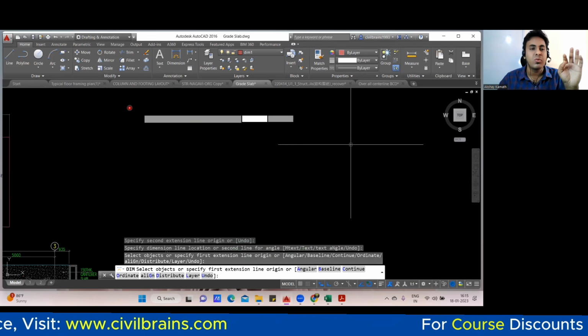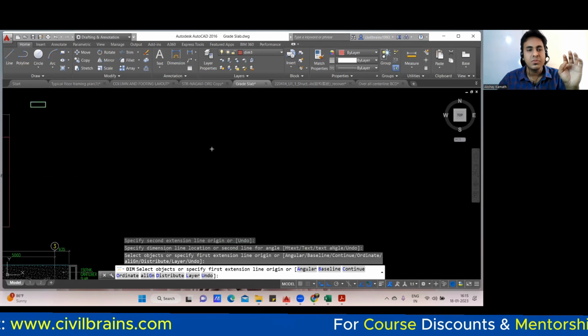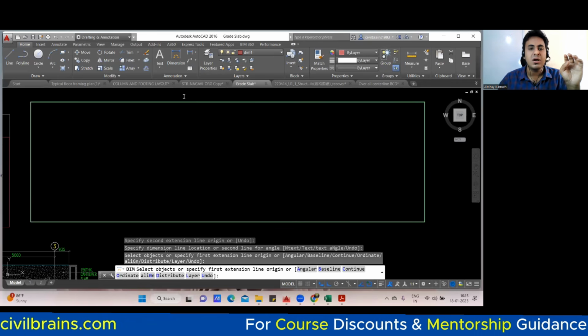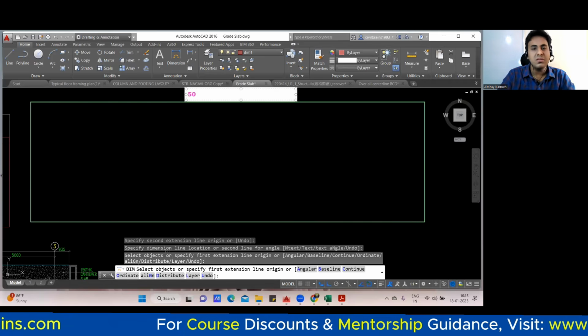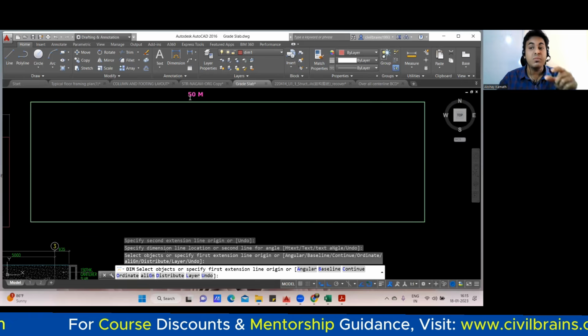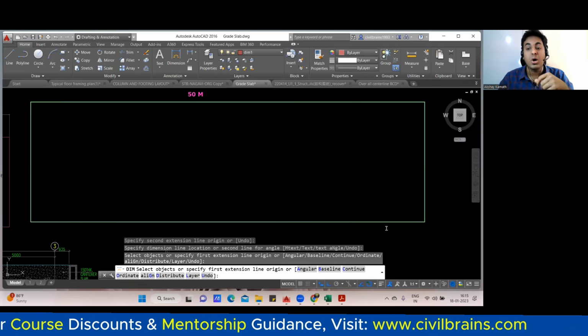Now let me give you one more case. The case is that let us consider I have one more footing. This is one more footing. Okay. And let us say this is 50 meter. So now what will happen? Again, same bar will go same only. But how many lapping will come? Because 50 meter is a span of your footing and one bar is 12 meters. So how many laps will come?